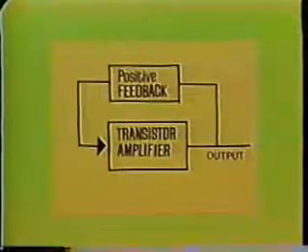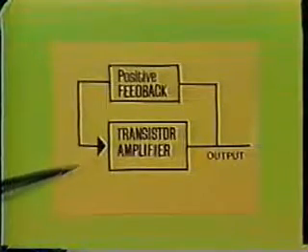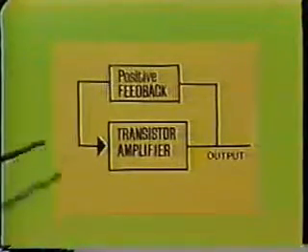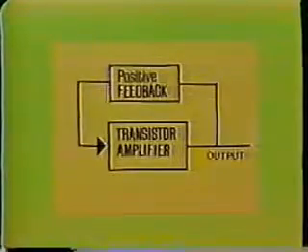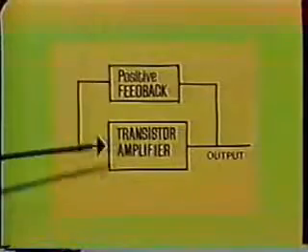All positive feedback is not bad, however. Positive feedback is necessary in oscillator circuits. In a properly designed oscillator circuit, it is not necessary to have an external input signal applied, but the circuit will begin to oscillate of its own accord when the output is connected to the input. Transistors are ideally suited for oscillators as they have a natural tendency to oscillate.